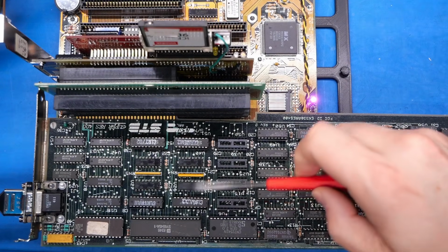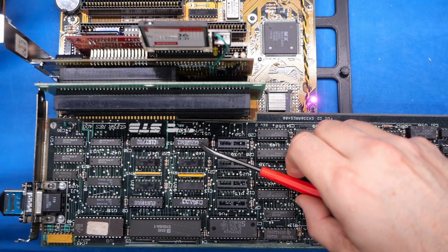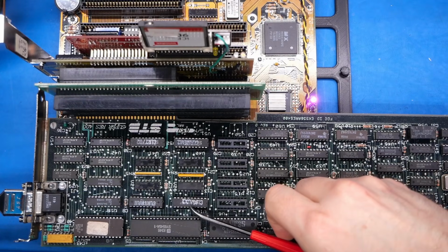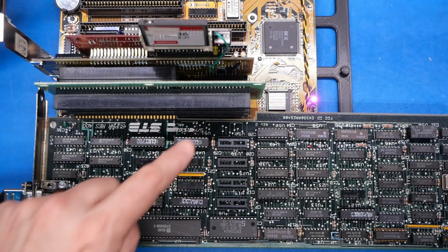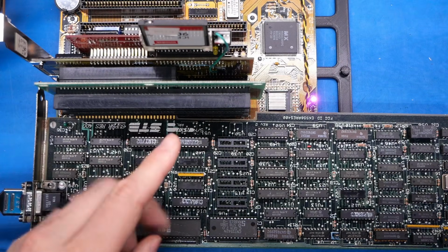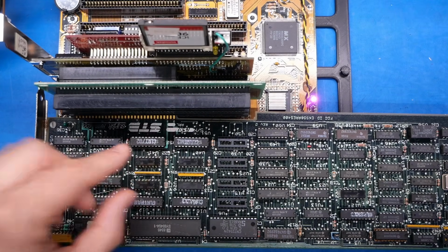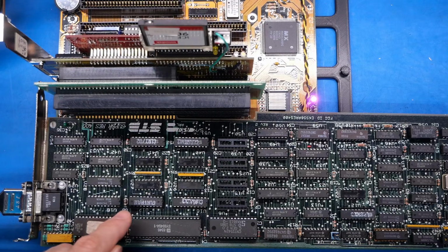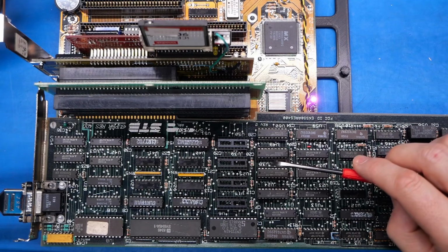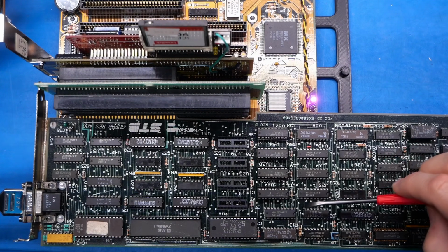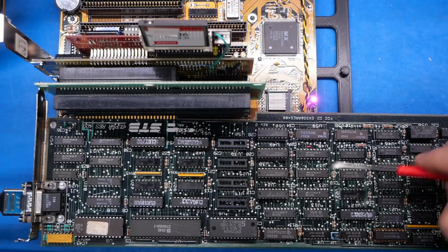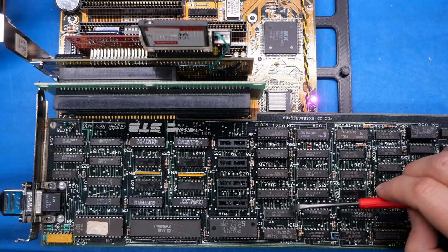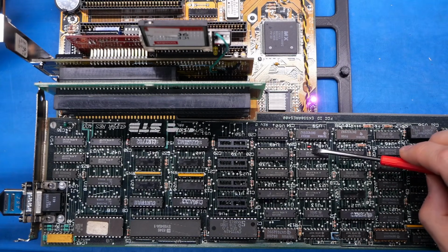And then on this part of the card here, we have these GAL chips, and this one says clock mem, I don't know, clock mux, and clock ras, and so these have something to do with obviously reducing the complexity of this card and probably doing the line doubling and other things that are happening on this card. So I'm thinking that the issue has got to be probably with one of these chips here, or potentially one of these chips, but I'm kind of feeling like it might be these right here.